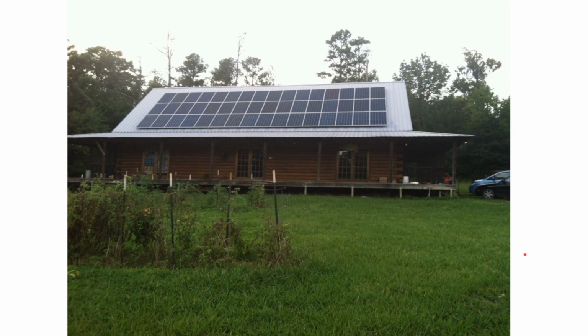A pre-built roof is not intended to be a construction site. Clearances around skylights or other roof-mounted equipment become walkways for solar construction workers during construction. When leaks do occur, it's usually in those walkable areas rather than within the array perimeter itself. Shingles in particular do not take much wear and tear, but a well-built solar array should extend the life of the roof.